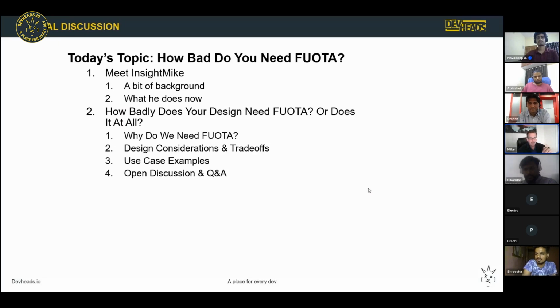So as soon as you get into a Linux device, if it's going to be attached to any kind of network, you really have to be able to support FOTA for that reason. But it's much easier to do if you're a Linux device. You're very likely not battery powered, or maybe you're solar and battery powered, so you're no longer talking about a tiny little battery. You're talking about a significant battery, or a network attached device. Those devices absolutely need FOTA capability, and it shouldn't be overlooked. Otherwise, you're going to have a security problem. You're basically creating a latent security problem in the field. So that's the most common use case to me.